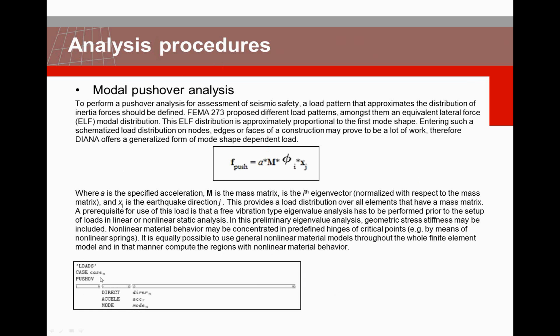We have made a function for automatically and easily generating element loads and nodal loads for a pushover analysis. The user performs an eigenvalue analysis, selects an eigenmode, and can refer to that mode in the load definition in, for example, a nonlinear pushover analysis.